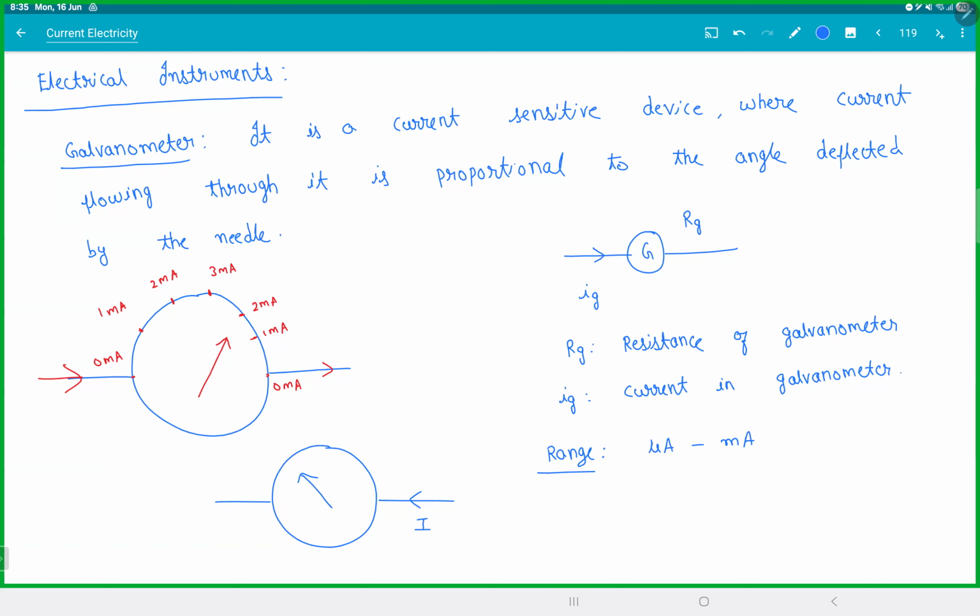If you look at your house AC, AC takes almost 16 amperes of current. So galvanometers, these things are pretty bad, right? They cannot withstand large currents. And sometimes they'll use the word full scale deflection. Full scale deflection meaning the maximum IG in the current. So maximum current is flowing in the circuit, meaning anything more than this, the circuit will burn down.